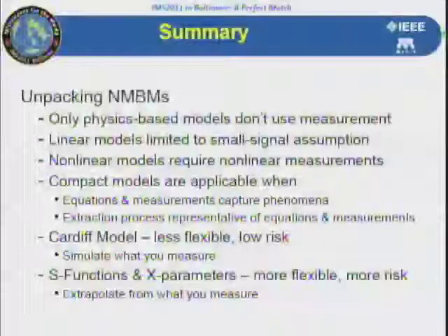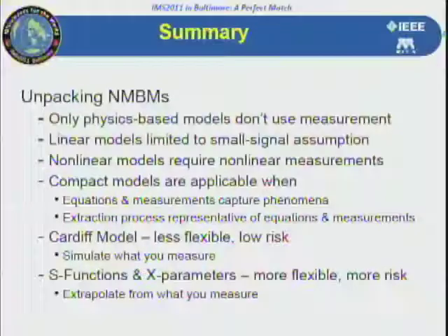So in conclusion, unpacking nonlinear measurement-based models, we've been doing this for years. The exception to measurement-based models, in the very least, are the physics-based models. Maybe there's another class somebody can teach me about of models that I'm unfamiliar with that don't require measurement. Linear models, S parameters, require measurement. They're limited to where the small signal assumption holds or where superposition holds. But as we grow the input signal or as we get frequency mixing effects, we need to go to nonlinear models, but they require nonlinear measurements.